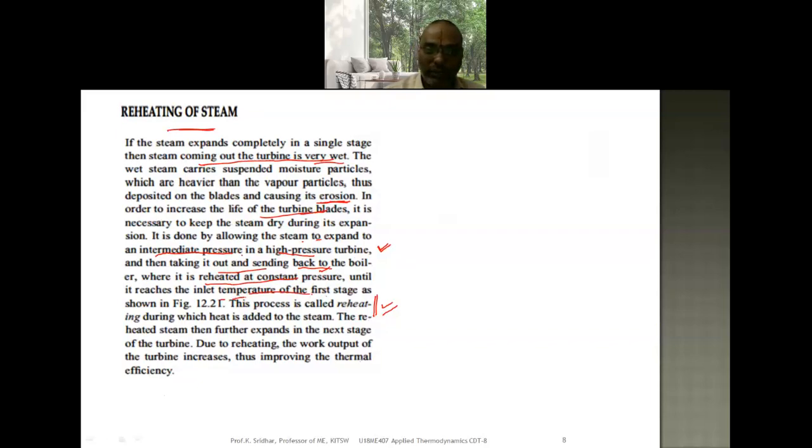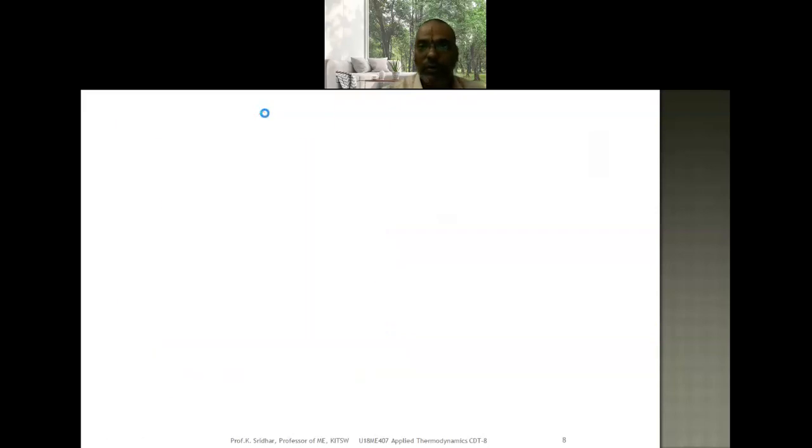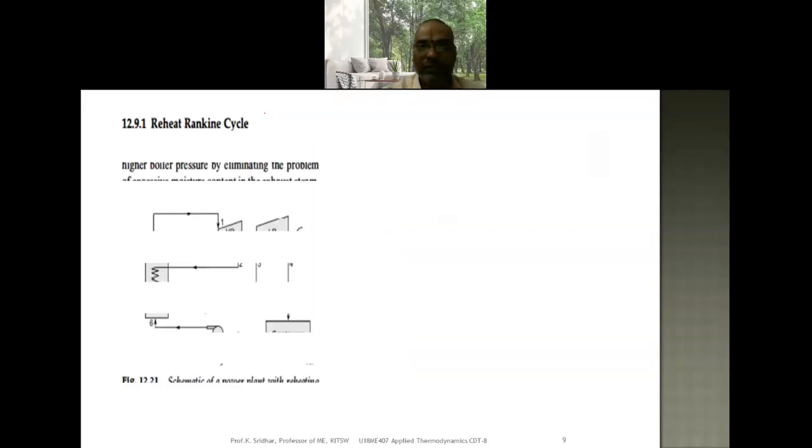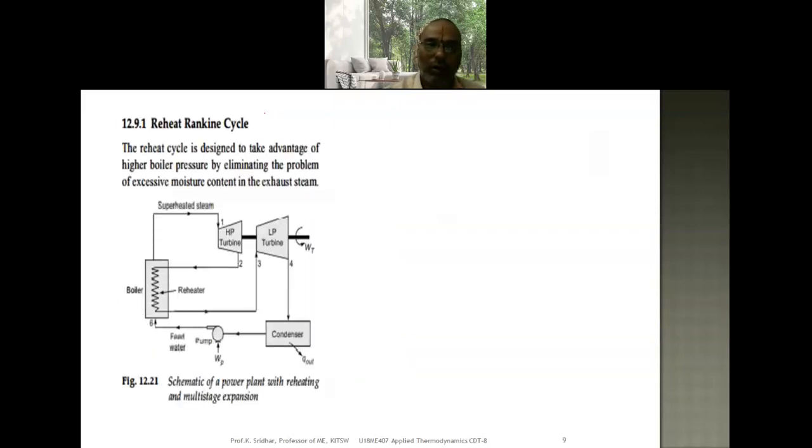So what are the advantages of reheating? In the last sentence you are able to witness here, due to reheating, the work output of the turbine increases and the thermal efficiency also improves. So reheating of the steam is always desirable to increase the plant efficiency and to increase the turbine output.